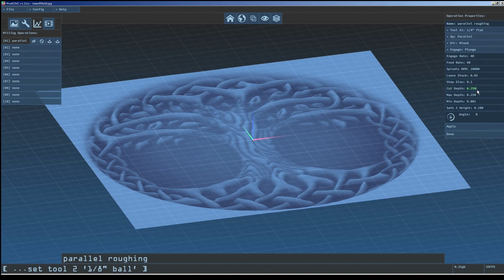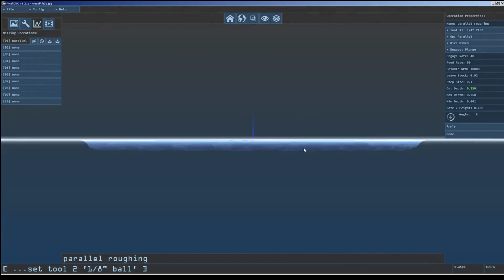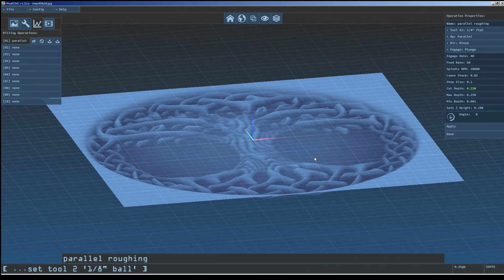By using a 1/4 inch cut depth, the end mill will dig deep and be able to cut the full depth of our project with each cut. This means that there will only be one layer of cuts and no retreading previous cuts to reach deeper into our material. If our project were deeper, a 1/4 inch cut depth would necessitate multiple layers of cuts up until the tool reaches the bottom of the project.